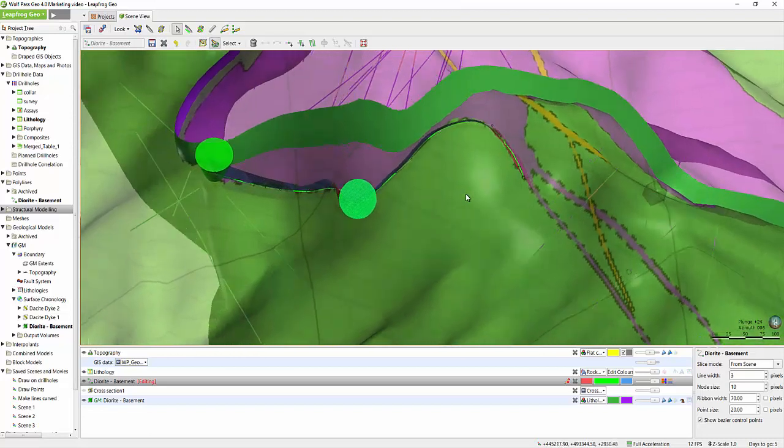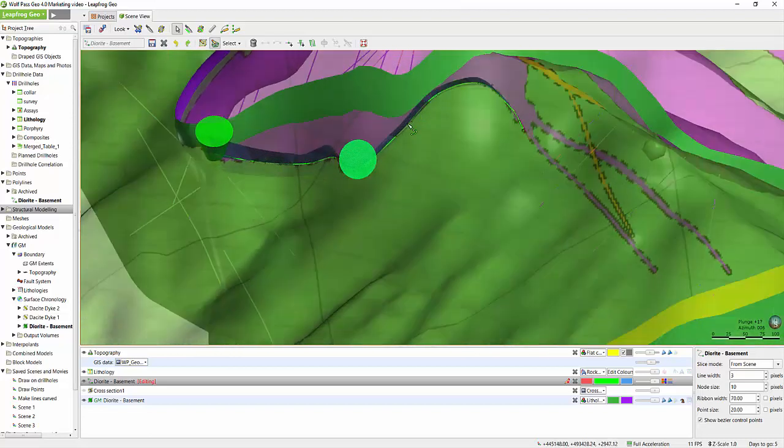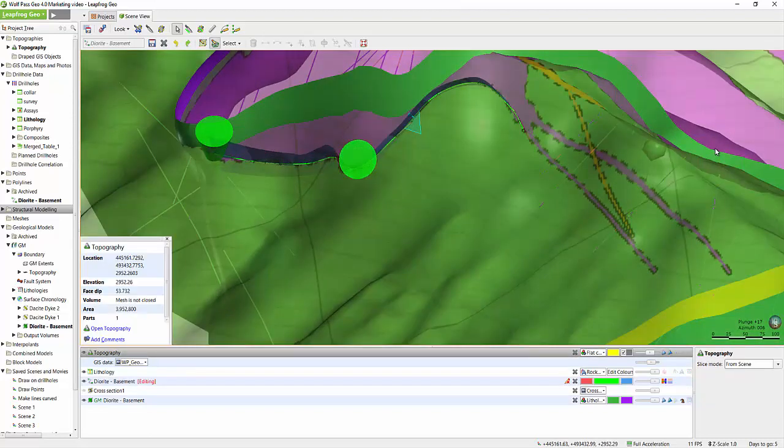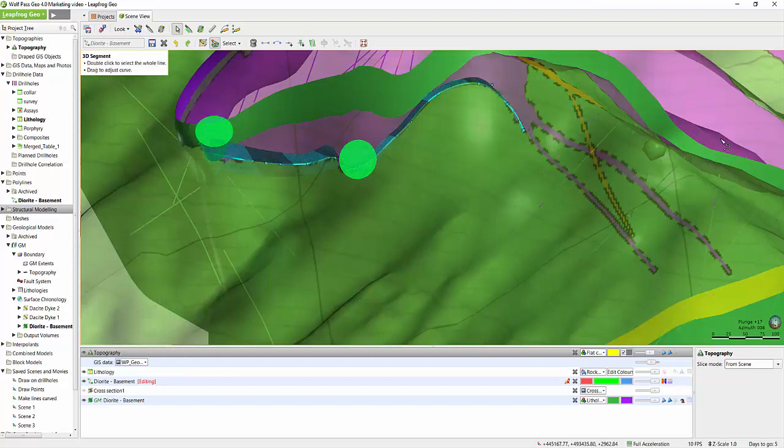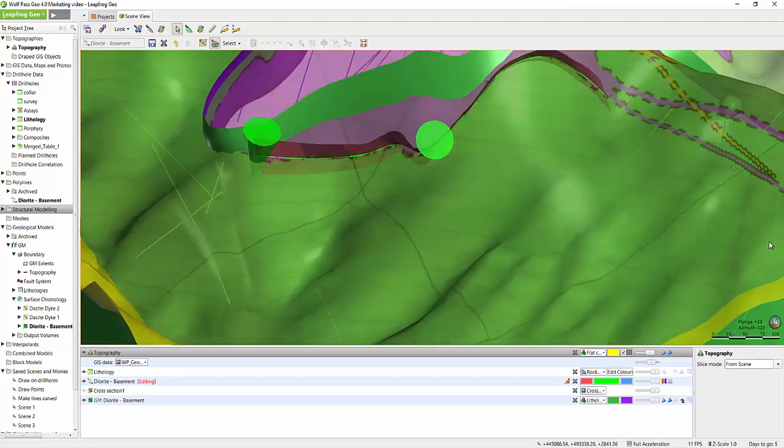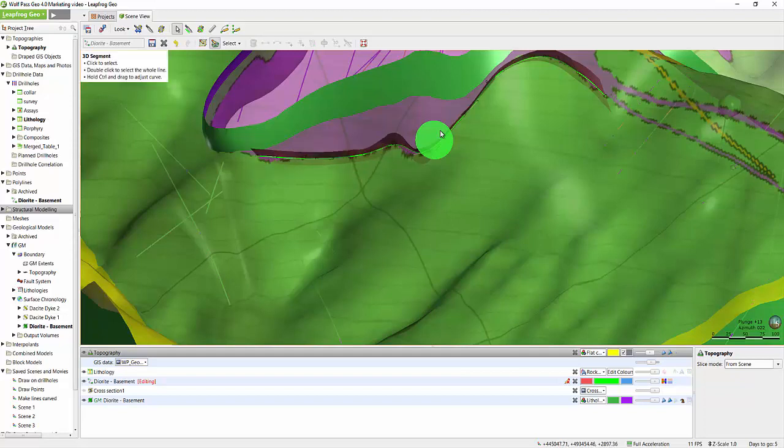That has affected the orientation of that ribbon. To flip the polarity of this entire polyline, double-click it so the entire polyline becomes selected. At this point, I can select this Flip to flip the polarity of that polyline. If I would like to remove these tangents altogether, I can simply select the tangent and click Delete.